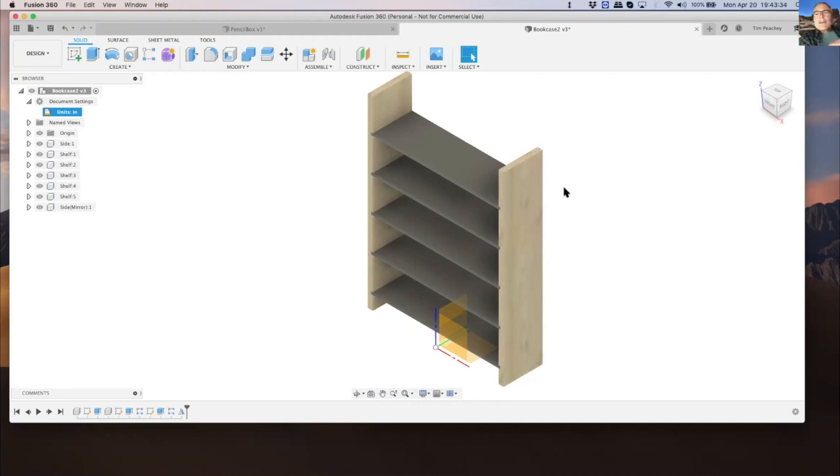So Tim, this actually takes us back to the very, very beginning, because when you chose, your intent was to make this thing symmetrical along the green axis. Correct. Because you knew down the road you would want to use this mirror feature, and you would be using that axis to be the center point of the mirror. Is that right? Correct. Now, if I hadn't done that, there's still things I could do.